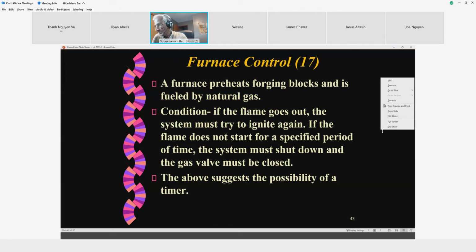The ignition system is sparking, so it has its own electronics. But as a safety, something is looking at the flame. Either the flame doesn't come or the flame comes and then dies. What should you do? If the flame dies, retry.